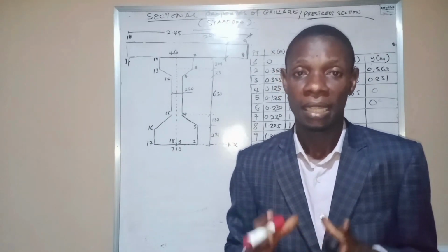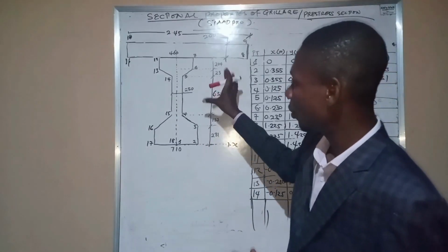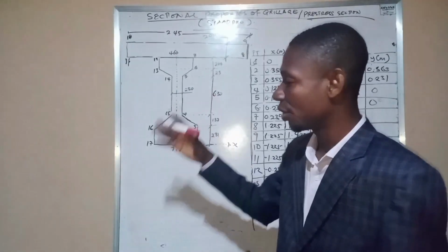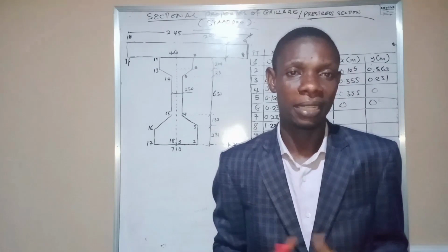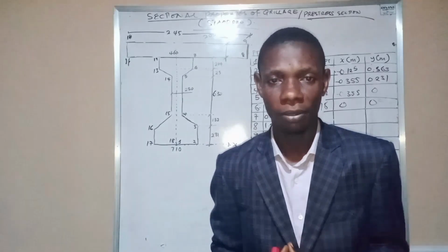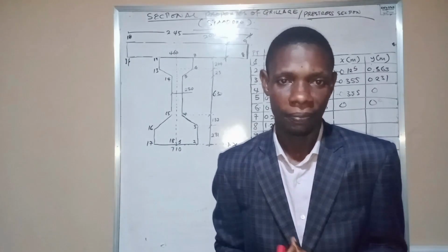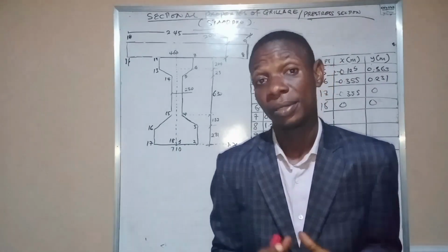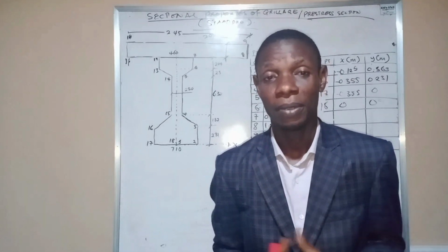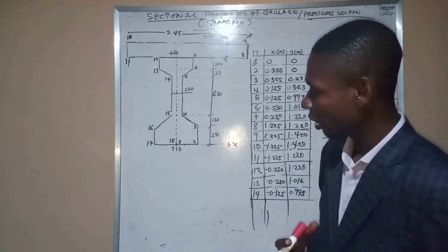When you do that, you can only do that successfully by applying the formula that connects the penultimate beam and the edge beam. Once you apply that formula, you convert the entire bridge superstructure into an orthotropic plate, and you can design it using the methods available, like the Morris and Little method of calculating the bending moment of a plate. All right. But we are not going to do the orthotropic plate method now. Subsequently, we'll have time to work on this. But let's get this section in STAAD.Pro for grillage analysis.